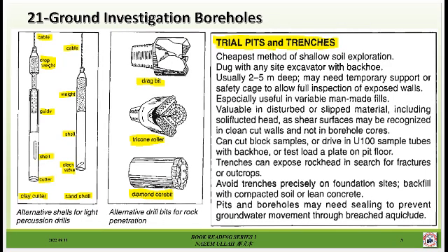Trial pits and trenches. The cheapest method of shallow soil exploration. Dug with any excavator with a backhoe. Usually 2 to 5 meters deep, may need temporary support or a safety cage to allow full inspection of exposed walls. Especially useful in variable made ground.